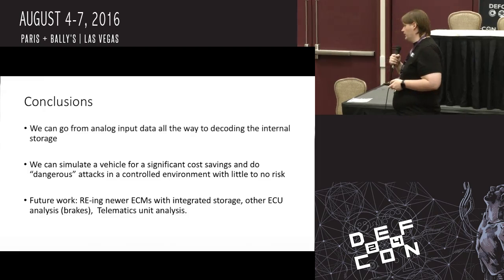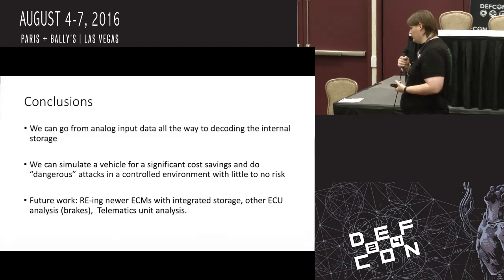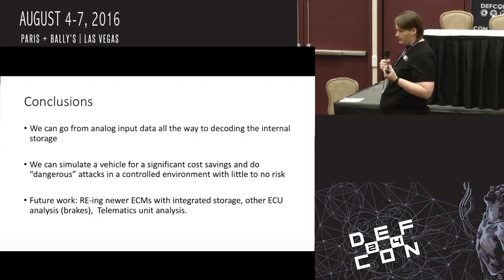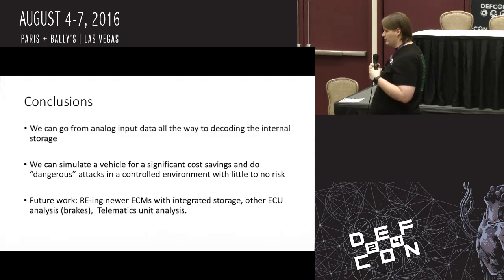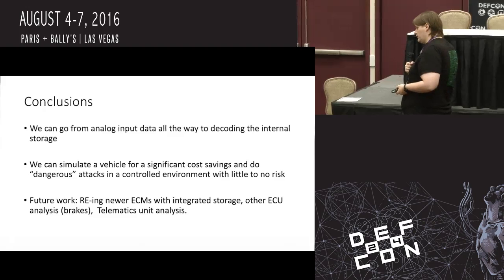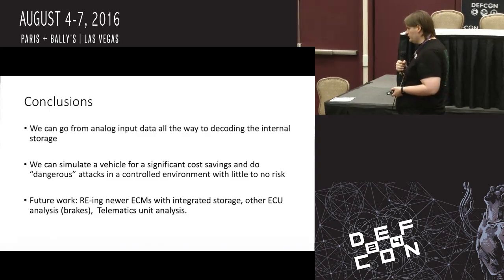For future work, we're looking at tearing open some of these newer ECMs. We were very lucky in that most of the older ones had a separate flash storage chip. Some of the newer ones integrate the flash storage into the same package or on the same die, and that makes it a lot harder. I can't just pull it out and stick it in a reader. We're looking at doing ECU analysis for some of the other units, like the brakes and the telematics units. So we hope to be presenting about that in the future.